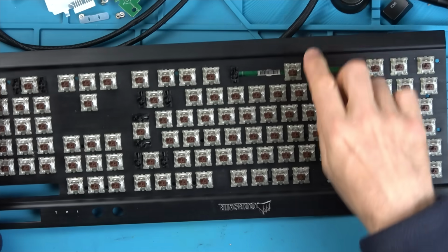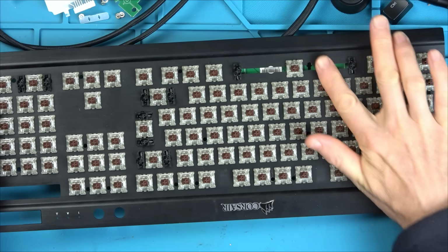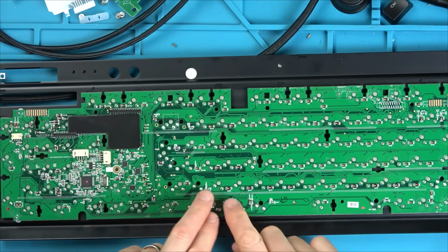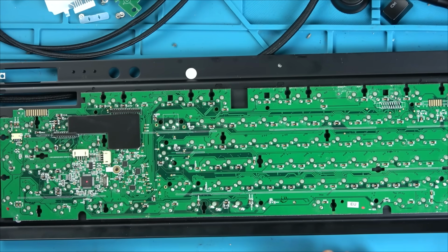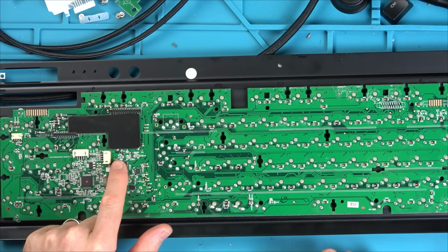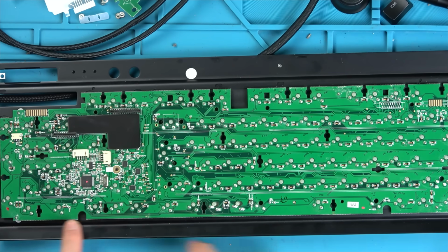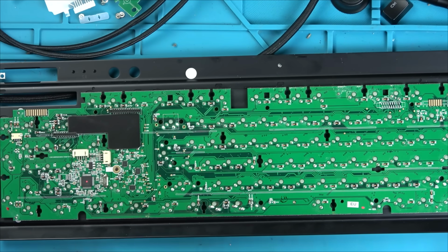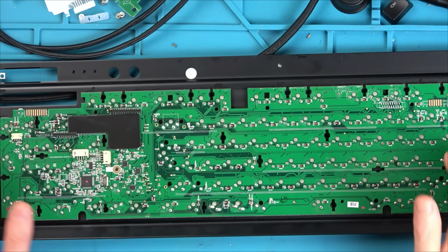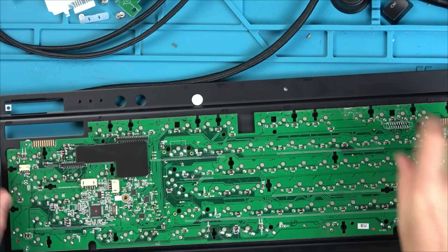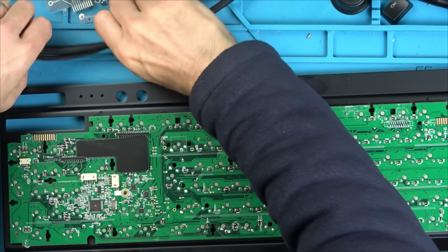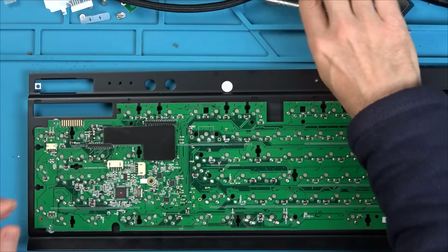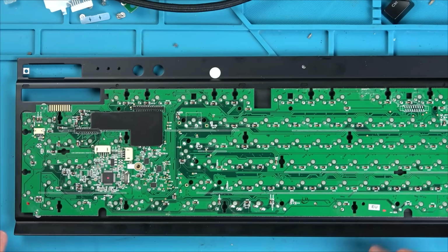If we still have the faulty ones here, going down here, and this one here, then I know it's nothing to do with the chips, and I know it's something to do with the traces, which I think is going to be the case. But it's much easier for me to just move these 3 around than undo every single key, because realistically that's going to take about an hour and a half of desoldering, I would think. So that's what I'm going to do to begin with: swap these chips about, and let's see if the problem is still the same as it is now.